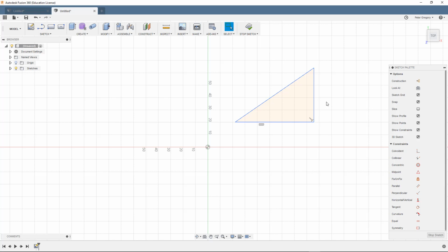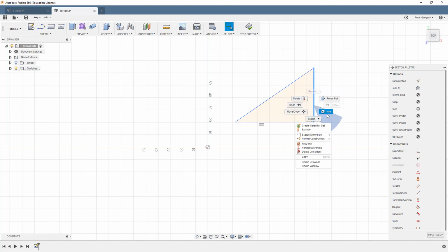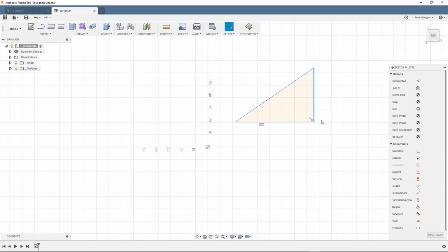It took me a while. I was way overthinking this, and I was thinking that there was going to be some kind of pop-up menu here that we could use to remove it. I thought maybe it was like a button, either on or off, like a radio button. So maybe what we would do is select these things, Control-select the other arm there, and then come down here and click perpendicular, and it yells at you. It says it's already perpendicular, so it's not an on-off kind of thing. And finally, I just tried selecting that symbol, click the symbol, delete, and away it goes.